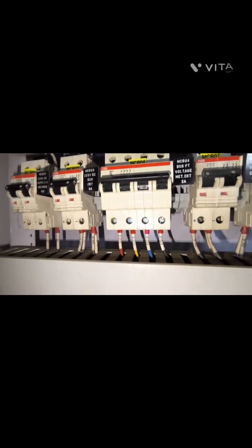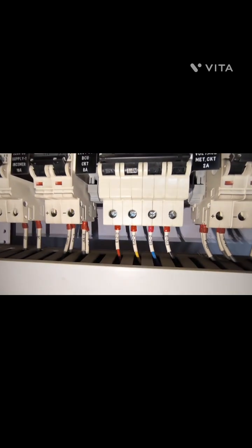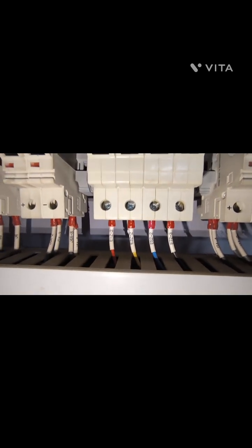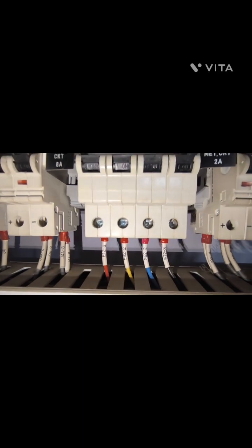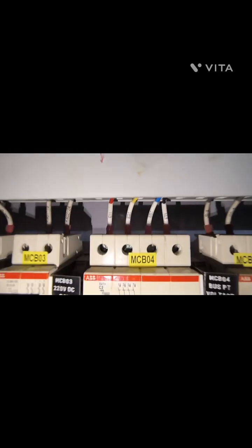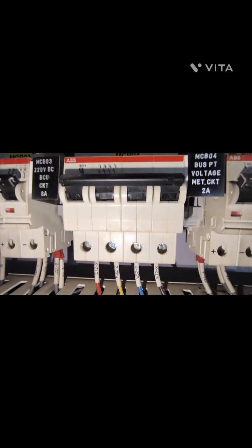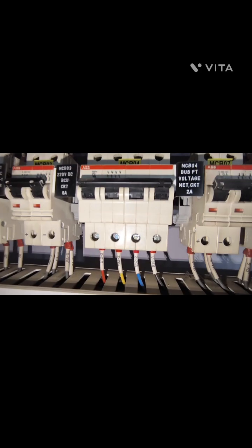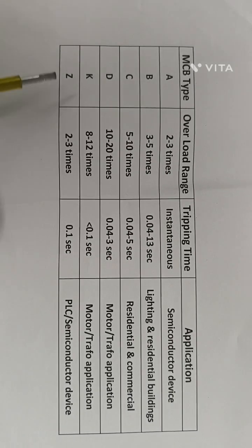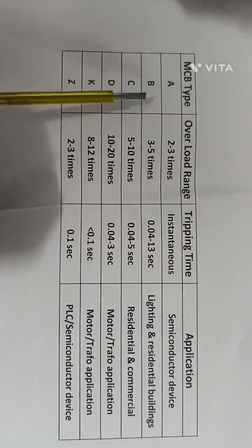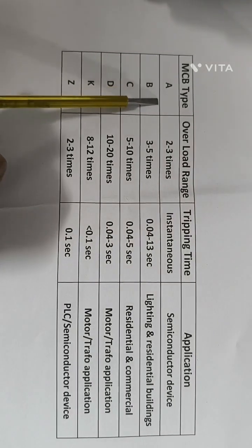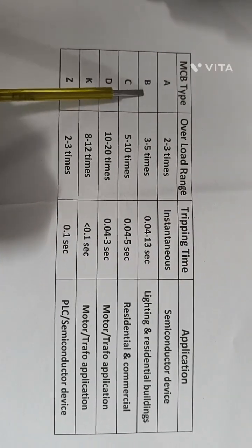Like that you can see here one MCB is there. That Ferrule starts with E. That is the PT MCB actually. The 4-pole MCB is there. E30, 11, 31, 51, 71. 4-pole MCB is there. This belongs to the PT core actually. So similar to that, Ferrule letters start with ABCD.